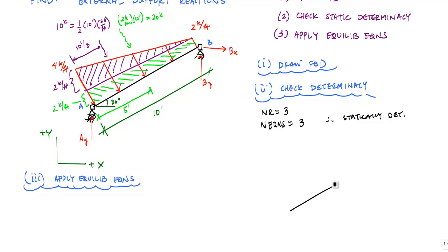Here is that beam segment, and then perpendicular to that I have a force, one of these resultants. I'm just going to draw a red line for that right here. And this is how I would resolve the geometry. This I know is 30 degrees, and one of the first things I like to do is draw vertical and horizontal lines at the point of intersection.